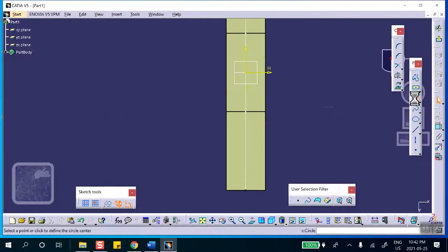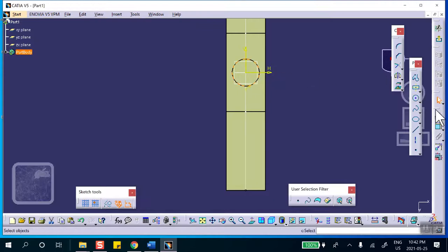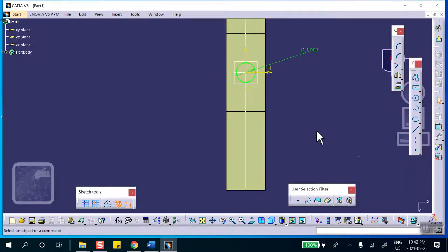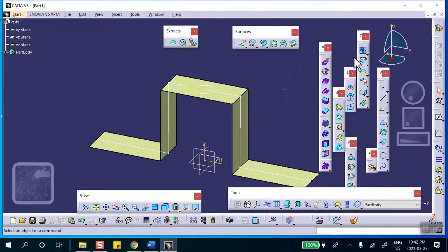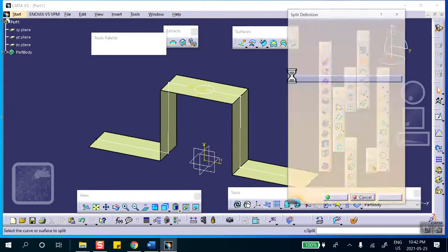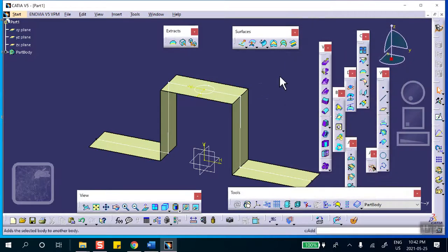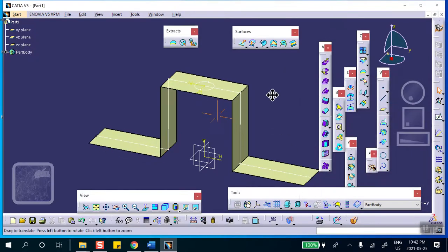I'm going to draw the circle, diameter 1. Diameter 1. Okay. And let me do exit. I'm going to split this. Split is right here, right underneath join. So you select the, oh, did I join? Actually, I really don't have to join here. That's okay. When in doubt, join it. You don't have to join in this problem, but when in doubt, join.